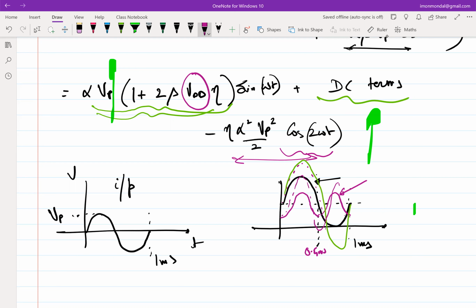This distortion component has come because of a squaring operation, which means if I increase my input amplitude by, let's say, 1 dB, the distortion will go by 2 dB, whereas the desired sinusoid will go by 1 dB. So that is why if you take any nonlinear system and crank up the input, you will see the effects of distortion, whatever it might be in terms of audio experience, it might be the shrill extra voice that you don't want to hear. Those things come up as you keep increasing the amplitude. If you turn the volume up, you will get higher and harder distortion.